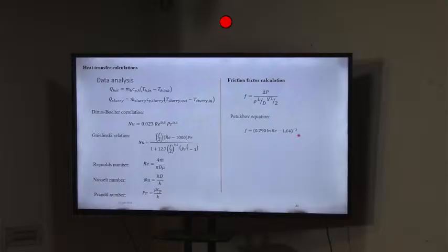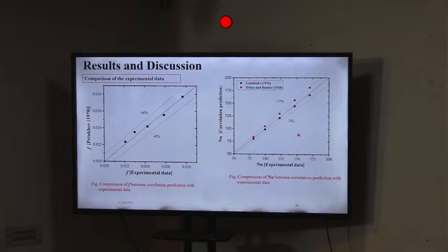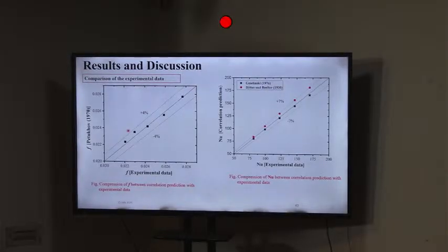For any heat exchanger, we find these non-dimensional numbers and the overall effectiveness. The results have been published, covering both heat transfer as well as pressure. The friction factor gives the signature of the pressure drop, and the Nusselt number is basically the heat transfer.